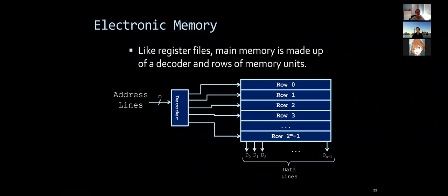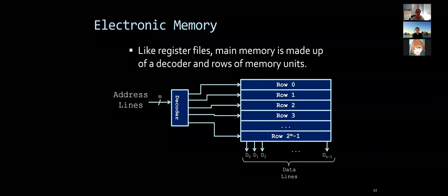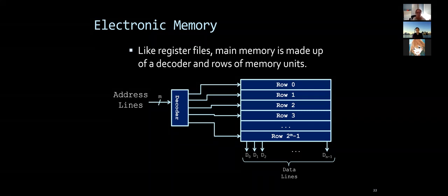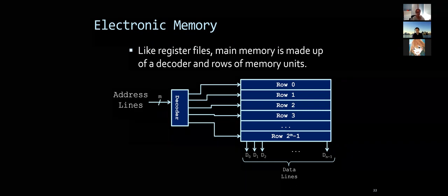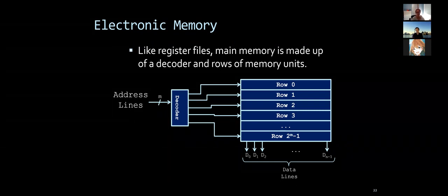For memory, instead of having all the individual wires for every cell as a single bit, I stored them in big chunks, like say 8 kilobits, 8,000 bits. And then we access them and select them afterwards. So essentially, you make them very small, and the processing logic, the decoder and the data read, is going to be shared. So when I read the data from DRAM, I really have the decoder and everything optimized to read one single row, 8 kilobytes at a time, but not the whole memory.